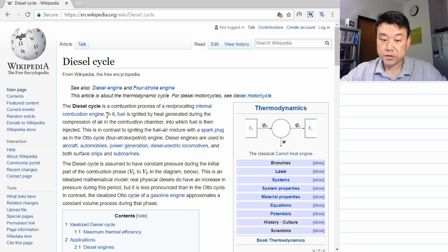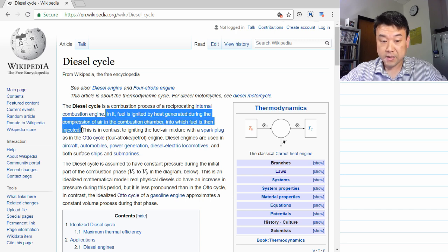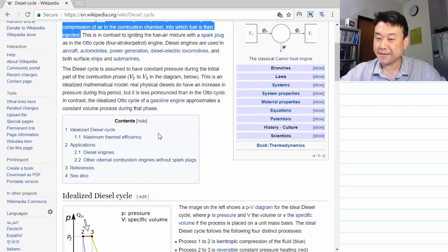And one interesting thing about the diesel engine is that the fuel is ignited by the temperature rise due to the adiabatic compression. You have seen that demo of the fire syringe, and it's not just a lecture demo. It is an integral part of an actual working heat engine. For our present purpose, what's more important is the cycle itself.